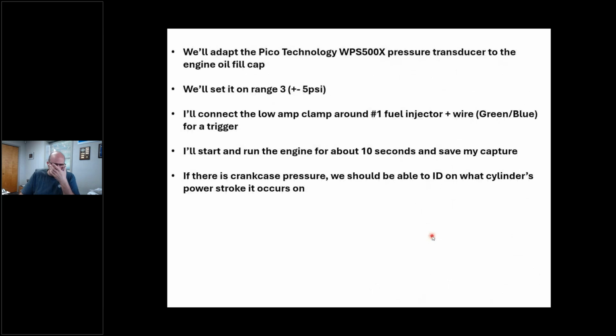All right. So what I'm going to do is I don't own any of that stuff, and chances are you don't either. But you know what? I've got a smoke machine in our shop. Okay, and I've got this Pico pressure transducer that I talked to you about, and we're going to use this to our advantage. All right. So what I'm going to do is I'm going to do a running crankcase pressure test here. All right, because I'm wondering if this thing has a crankcase leak in cylinder number 4.